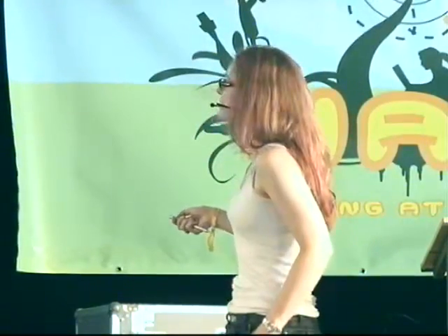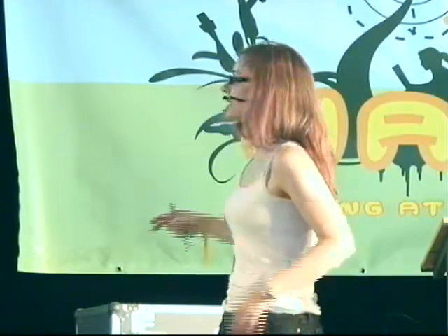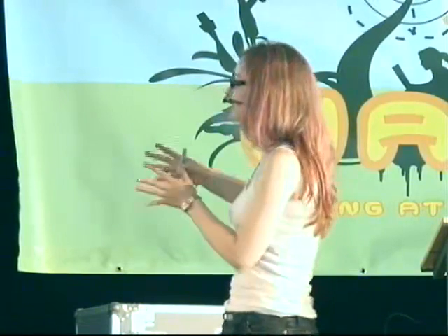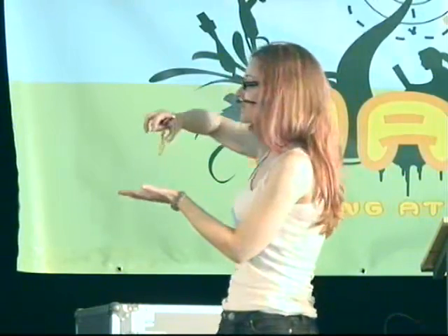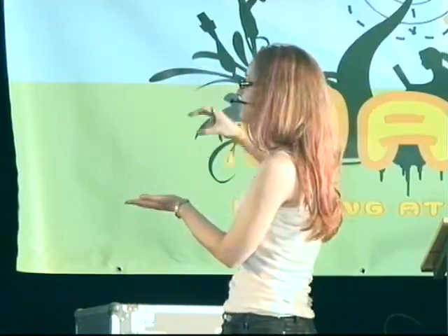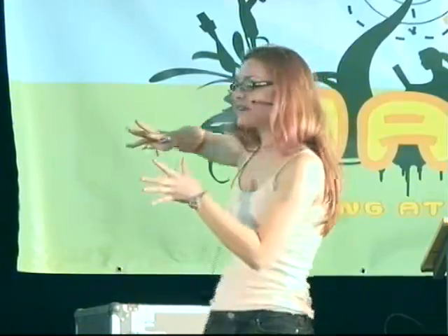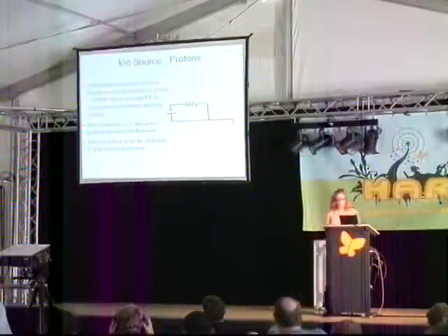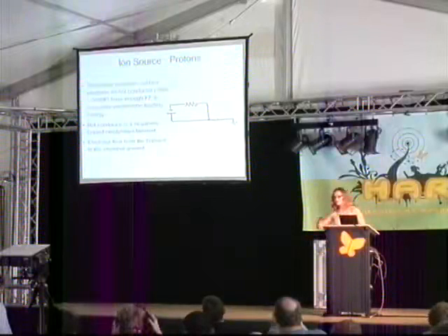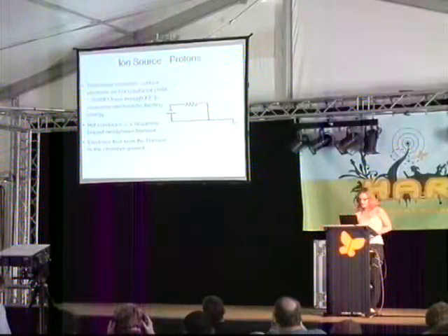That is negatively biased, so you apply your 10 volts, 15 volts to that. The electrons have enough kinetic energy, start jumping up, and because it's negatively biased, ground is positive for them, so they start jumping up towards your system ground. So you have a constant stream of electrons flowing from the hot filament to the system ground.